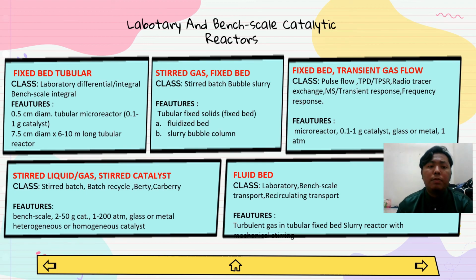What are the features of this item? It has a 0.5 centimeter diameter tubular microreactor, which handles 0.1 to 1 gram of catalyst, and we also have a 7.5 centimeter diameter, 6 to 10 meter long tubular reactor.